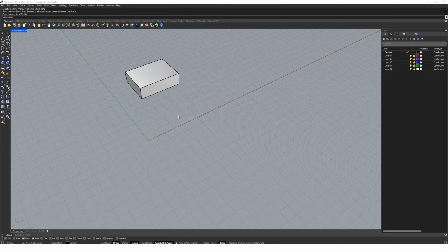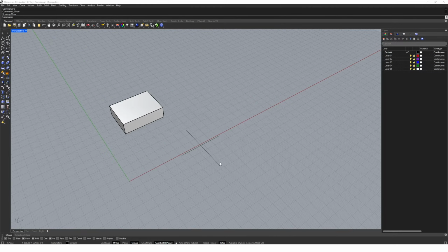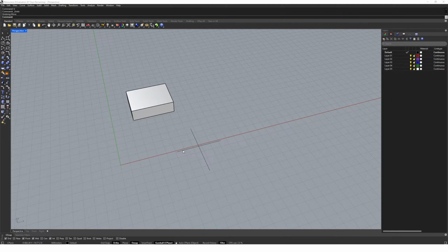We could also draw two lines that intersect and turn the intersect snap on. And then move from our endpoint to the intersection of those curves. I'm going to undo this and just slightly scale one of these curves so it's a bit longer. And then I'm going to turn on the perp snap and move this box so it aligns perpendicular to this curve we've created.